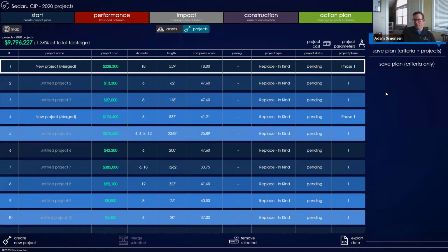So if I have sections of my system that are critical, that have low redundancy, they're going to have really high numbers of customers affected by losing service on that particular pipe, versus in a well-looped distribution system where if I lose that pipe, I'm really just affecting the people tied into it. And also, as Matt was talking about, considering valving into that as well, you can get a pretty accurate picture.